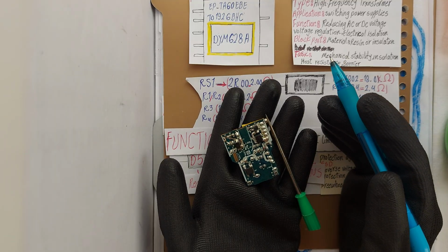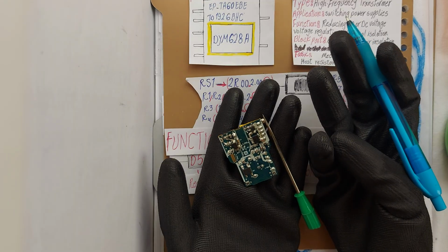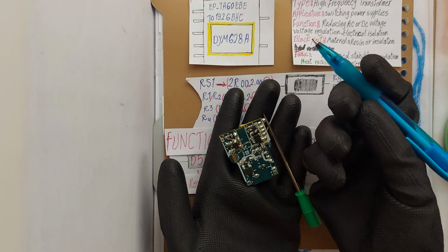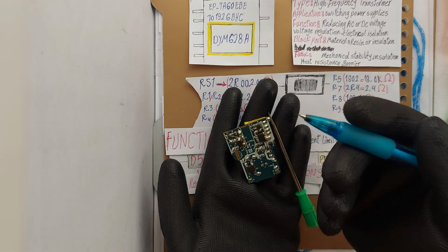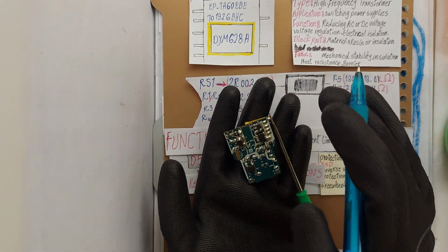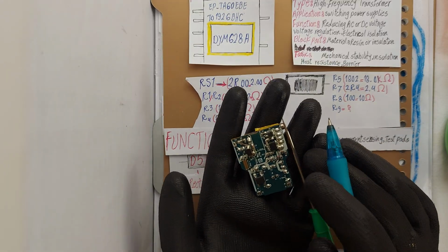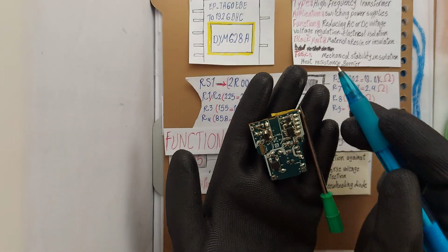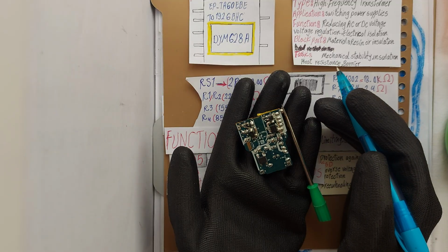Main roles of resistor in this circuit are dividing voltage to create a reference or feedback for ICs, limiting current in the input or output paths, current sensing for control and protection, serving as test points for measuring voltage or current during factory tests or repairs. Let's examine the resistor on the board. At the first, we have RS1 right here, as you can see. So, 2 ohm test point for measuring output voltage or current sensing resistor.